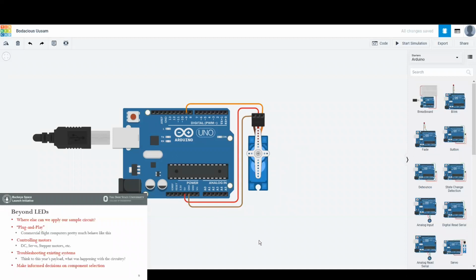However, one thing before we move on, I would not recommend connecting the servo directly to your Arduino. It might be okay, but like I said, 40 milliamps is the max. I believe off the 5-volt pin, it's 500 milliamps, or maybe 1 amp for the Uno. So it might be okay, but if you're powering anything bigger, you're going to want to have a separate power circuit. But for now, we're just going to run with this.